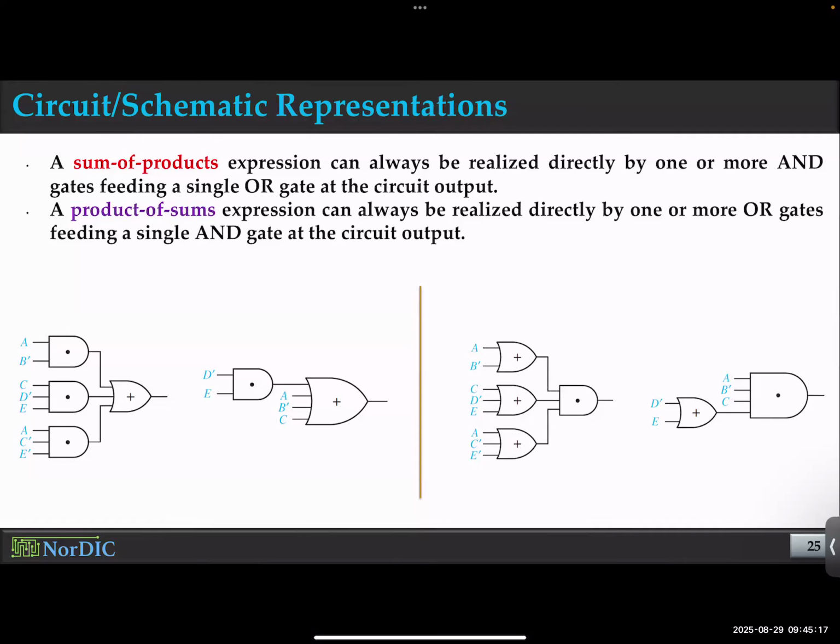So if you are a company that makes a small part of the circuit and you keep making this sum of product format hardware, if I give you more inputs, you just put in 0 or 1. Does that make sense? Or just keep them floating if you want to. We don't keep them floating, but apparently you could just do something with it. You can always make all the logic layers 4 input, 4 input, 4 input, and final OR gate 4 input. Say that's like an FPGA, for example. Programmable, you could use it for whatever you want to control. But I'm gonna just make this circuit forever. It's easy for you to make. Versus if you need to custom make every circuit for every application, it's gonna take more money and more effort.